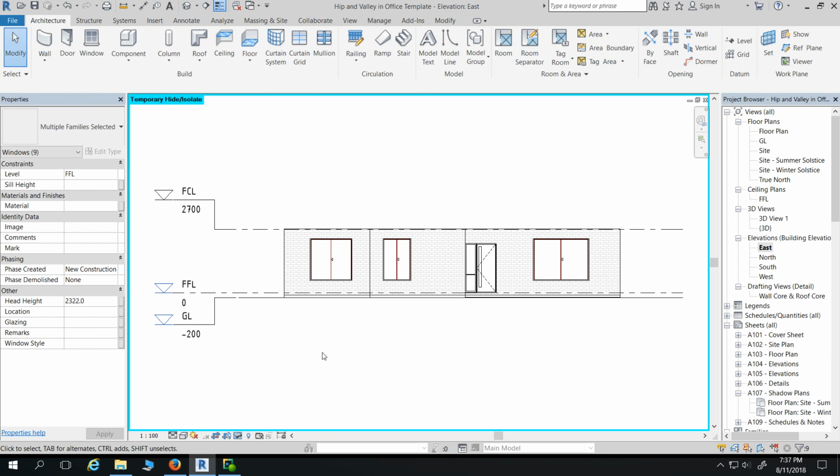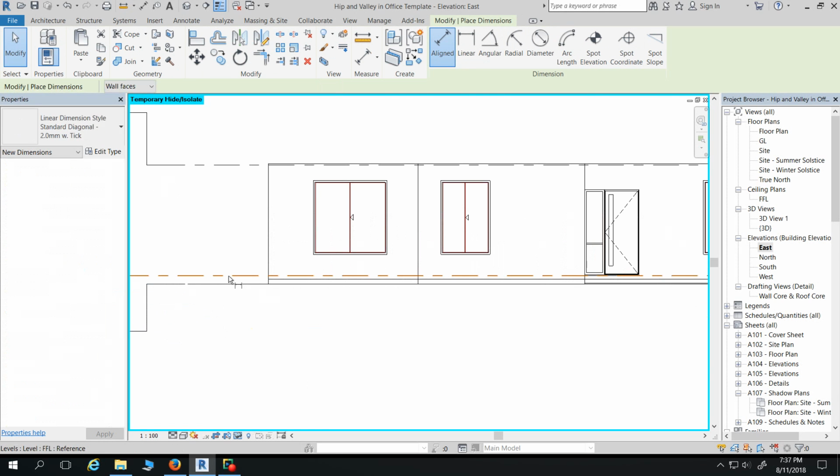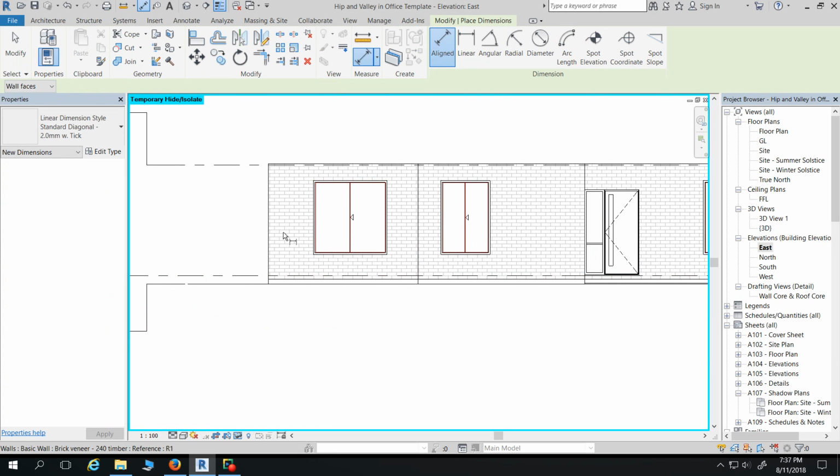So you can measure from, if I measure from there, whoops. Does anyone want to have a guess of what was wrong now in elevation? Our west elevation? Yeah, because it's a window. So this is a bit of an issue of doing it this way. That filter doesn't discriminate, it just selects all the windows. You can't even then filter it down to say I want to select these awning windows, like all the awning windows I want to have at this.